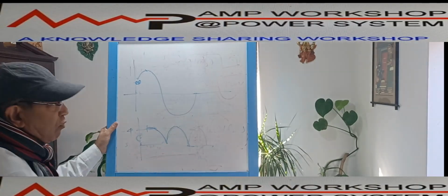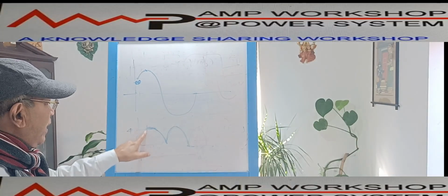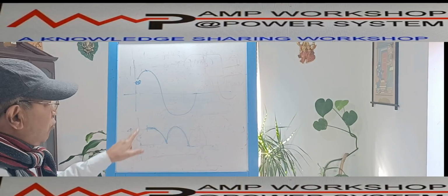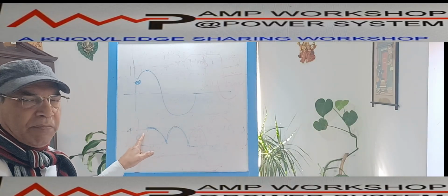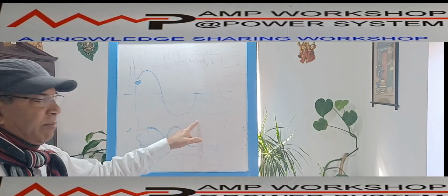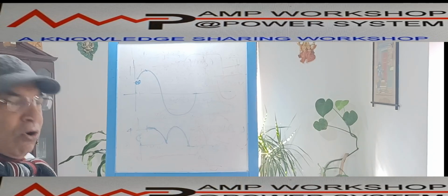So if we want to control the DC output, I can use the thyristor by chopping this part. That's why, as the starting of the rectifier can be controlled by the gate terminal, we call it a controlled rectifier. Okay, these are the controlled rectifiers.